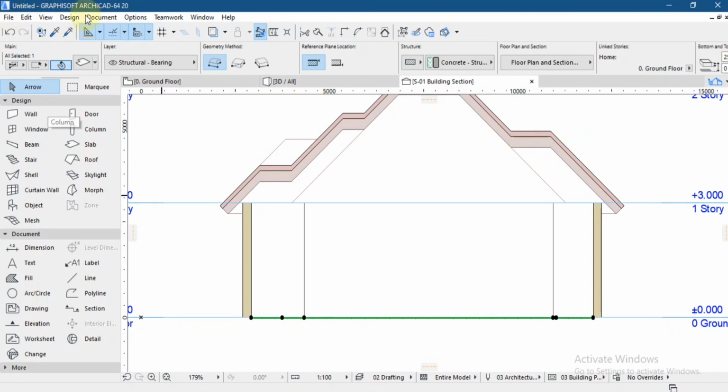So now, ceilings usually have an offset of 300 mm. Like the ceiling noggins extend 300 mm downwards. It can be 4, it can be 6, but normally the minimum is 300. So we do 300. We're going to carry this up to that 300 mm line. So, okay, let me show you guys how I got the line.